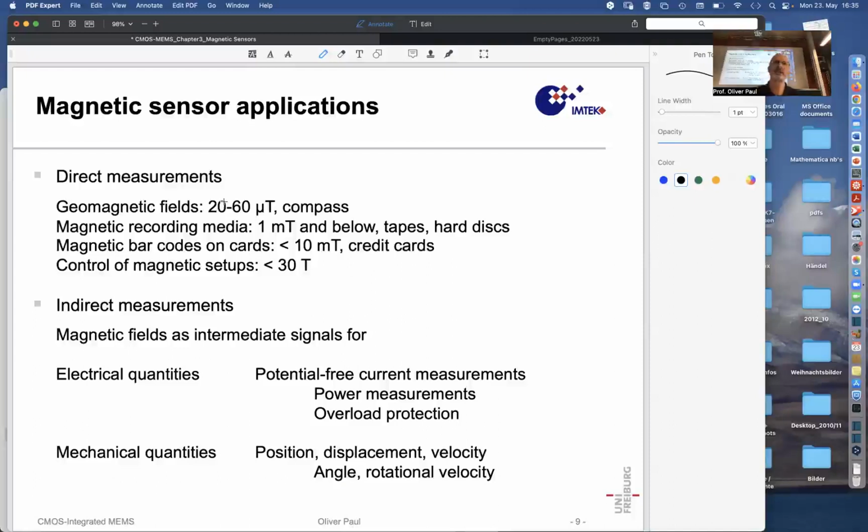So compasses with just a silicon sensor, as I described, are difficult to fabricate, because noise in circuitry is easily of the order of microtesla. Sorry, these signals produce Hall signals, as we will learn how to calculate, of the order of microvolts.